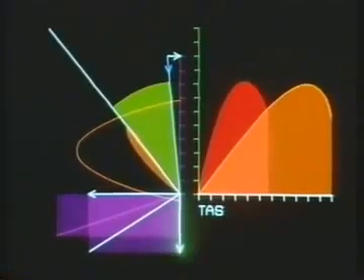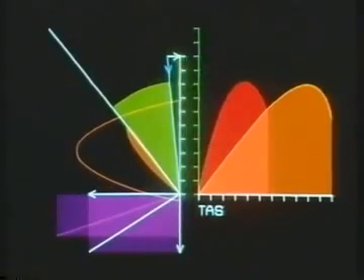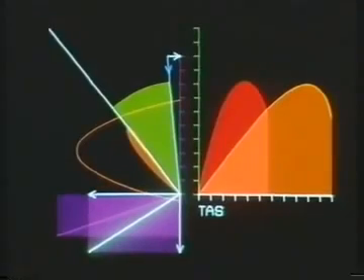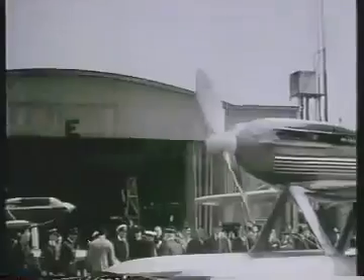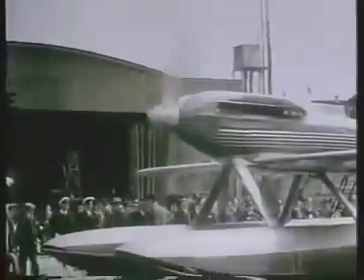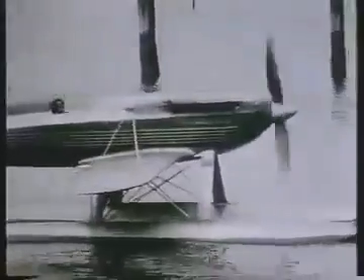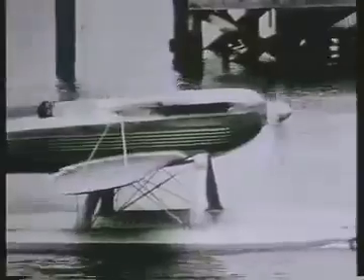Torque would be high, so RPM would be low, and because the direction of the total reaction is further from the direction of flight, less thrust would be produced, and acceleration would be too slow for takeoff from normal airfields. The pitch of this propeller is very coarse. For the Supermarine S-6B was built to win the Schneider Trophy, and speed was all that mattered. But takeoff acceleration was very sluggish. So, like a duck, it took to the water for a runway of unlimited length.